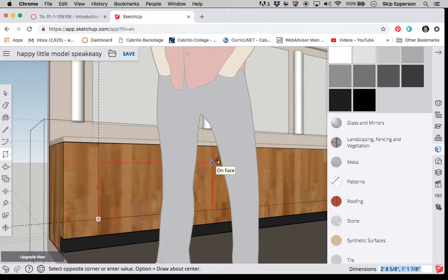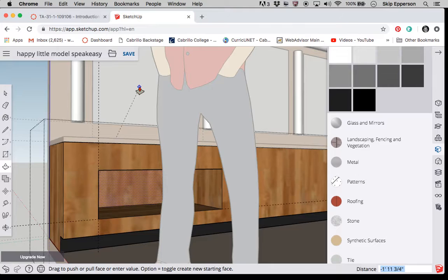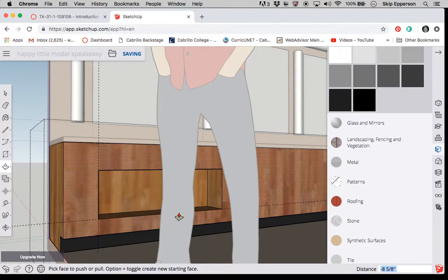And let's say I'm going to type in 3 feet wide and 12 inches tall. And I've established a panel here, but I want to recess that panel, so I'm going to click on it and push it in a little bit. Let's push it in 1 inch. Okay, return. And let me finish with that, and we'll be done.